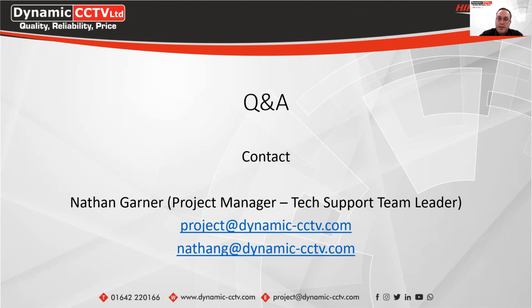Daniel has asked, can the door systems be linked to a fire system for automatic unlock during an alarm? So it is possible to wire fire alarm systems into the access controllers. There is a specific module within the Hikvision access controllers to take an alarm input from a fire alarm, and that will automatically open all the doors if the fire alarm has been triggered on the system for those.